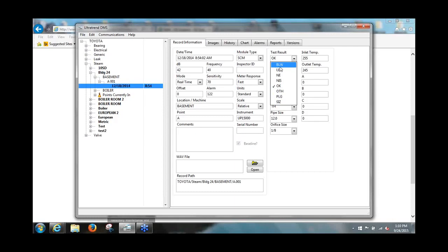So the main factors that you need to make the right call on for these traps to work on the report is knowing if it's blowing through, if it's wide open, leaking by like motorboarding or chattering, or if it's just cycling okay. Now the next one will be the manufacturer.